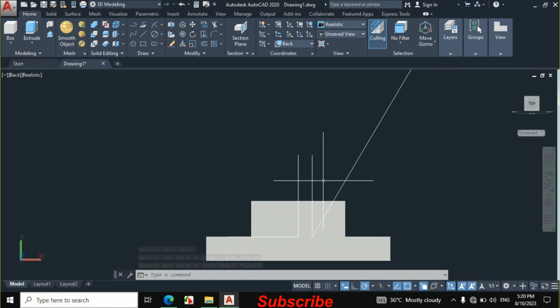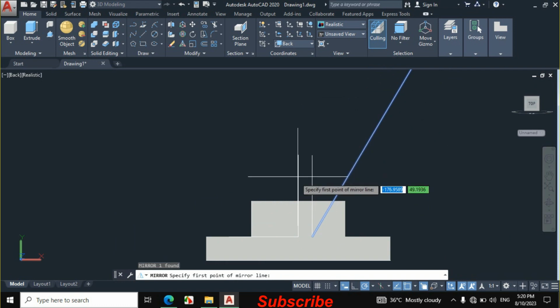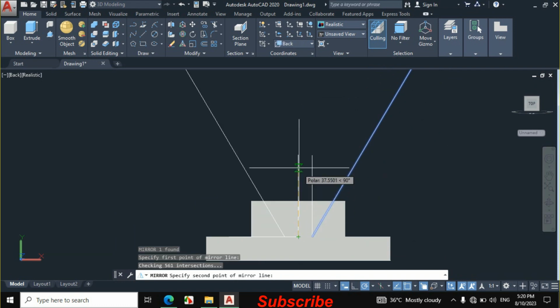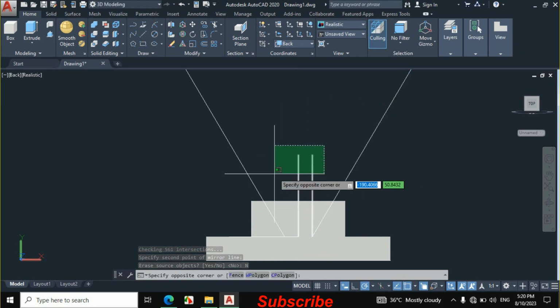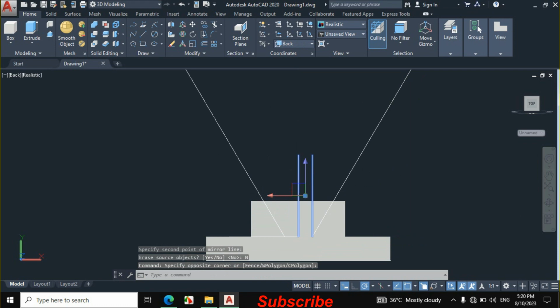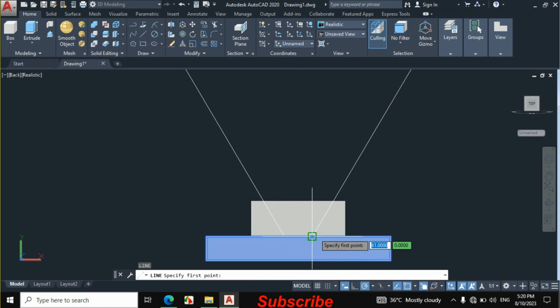Now select this line and press MI from the keyboard for mirror, and mirror this line about this center line. So this line is mirrored. Now select these two lines and erase them. Now again make a line, L, enter from the keyboard. Now join this line and this line.